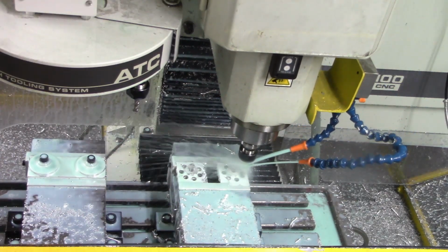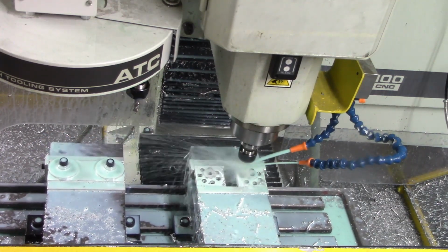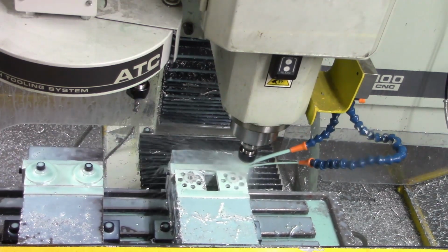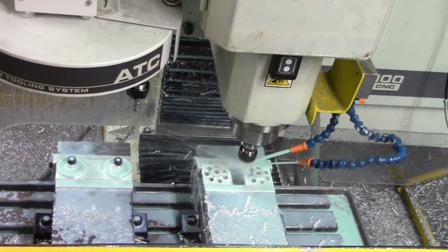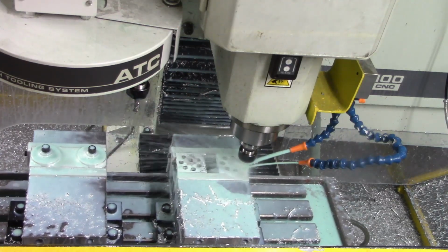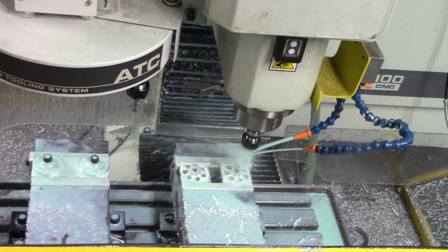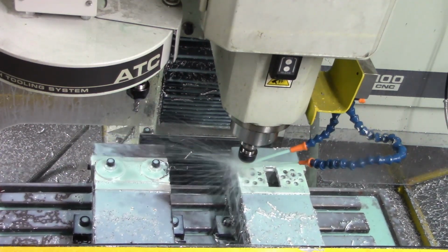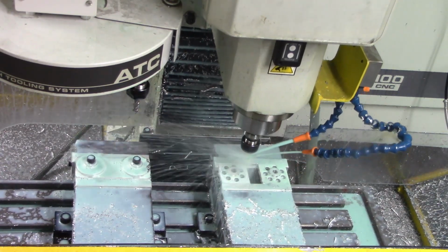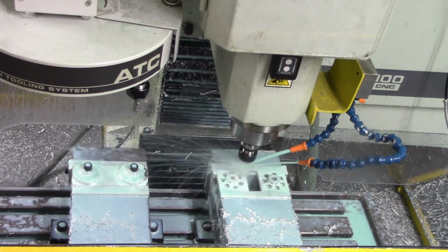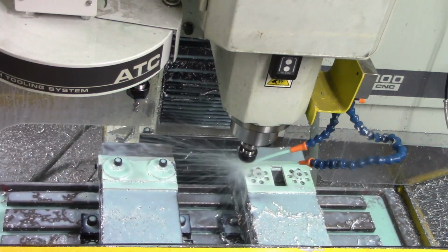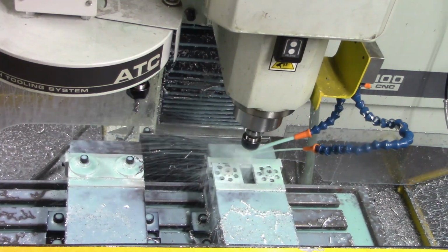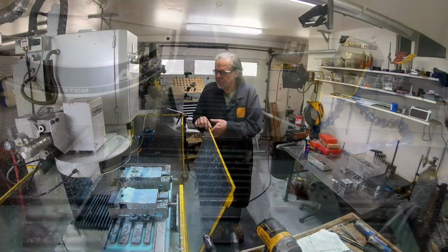And so by finishing after the drill operation, I get a tiny bit nicer surface finish, which is one of those little details. I have to do the tool change anyway. Doesn't really cost anything to modify the sequence in that way, but it does make the part come out a little cleaner, and it is a machine being sold to artists, and I consider myself an artist, and surface finish is important. Having the parts look nice is important.